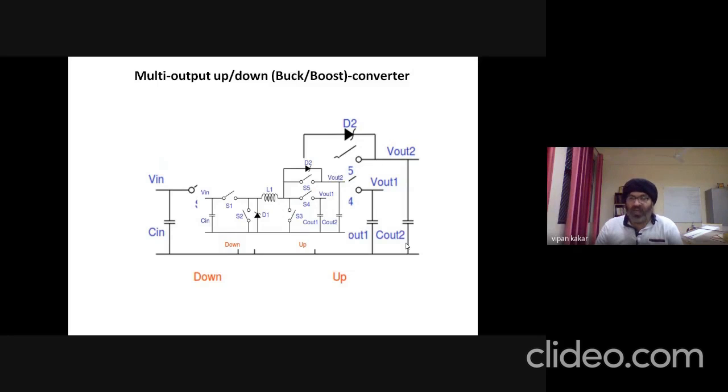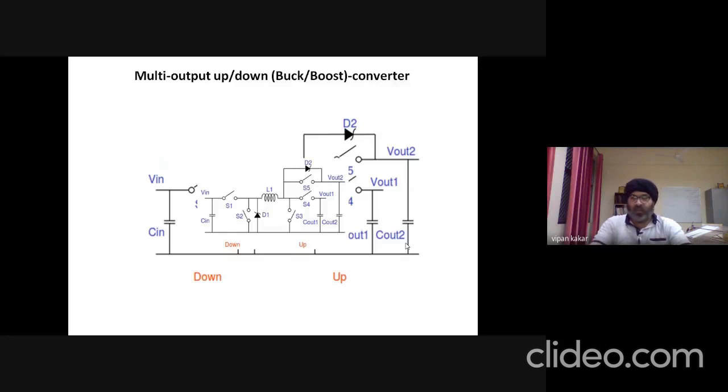And if we want to operate these converters in continuous mode where no standby phase is there, since the standby phase will save energy, save power, then only phase 1 and phase 2 will be applicable, where only NMOS and PMOS are in the picture. Okay, so with this, we come to the end of these DC to DC converters.